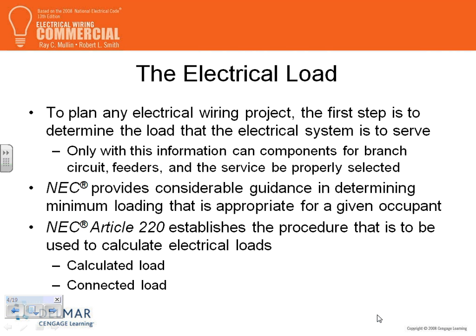A couple of things, guys, I'm just going to summarize the lighting calculation load. When you do the calculation, the first thing, Brad, is the lighting calculation. You need to find how much volt amp you need for that particular commercial building. Two ways we calculate this, if you guys remember. We did it with the actual load when we know it, and we did it based on Table 220. In Table 220, we found the volt amp multiplied by the square foot of the building. That's the chunk for the light.